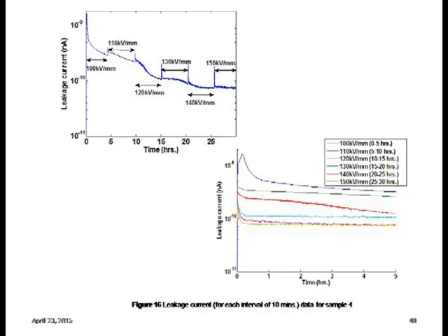So that's why people have come up with mixing LDPE with some nano powders, nano MgO, etc. It has been observed that the electrical breakdown strength and long-term performance improve. Of course, they have conducted experiments for 30 days or so, because we can't afford to conduct an experiment over 5 years or 10 years.